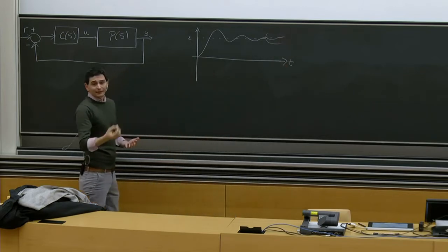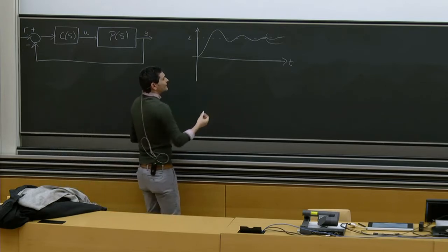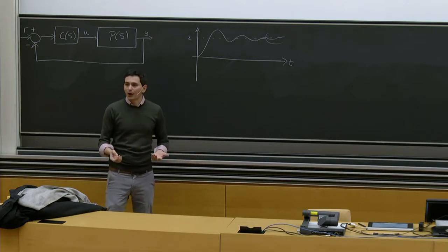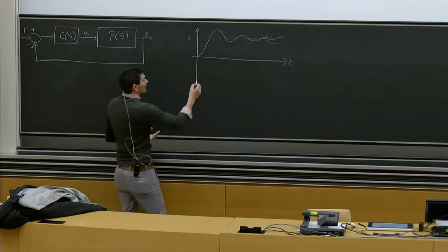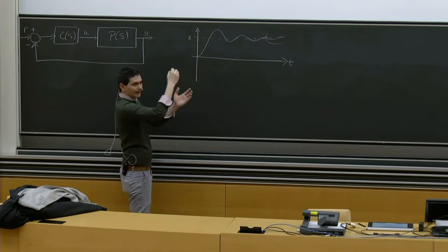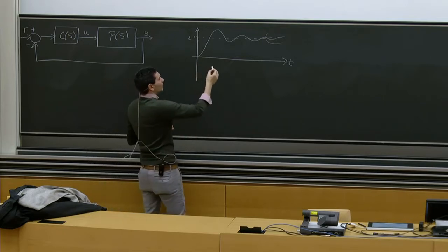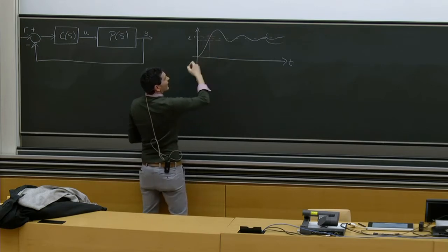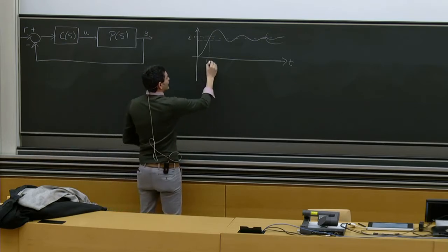And then there's the transient domain performances, which are basically things that tell us how quickly and how accurately, if we want, the system gets to where we want it to be, gets to the reference signal. So we defined, for example, by just defining an arbitrary band around what the unit input is, what the objective is, we said, okay, let's take, for example, the first instant at which the output of the system gets close enough to what we need as the rising time.